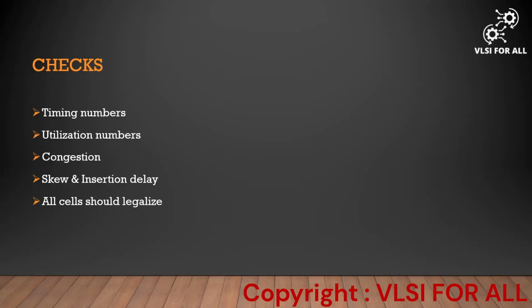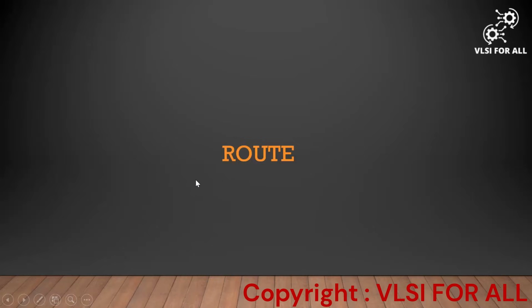Now checks. Once after doing the CTS and all, we have to check for the timing, utilization, congestion, skew, and insertion delay, whether they are meeting or not. All cells should be legalized. So these checks must be done after the CTS. Now moving to the route.